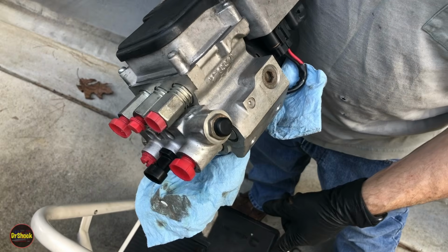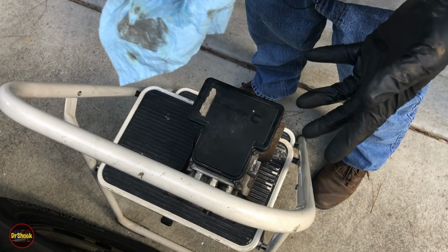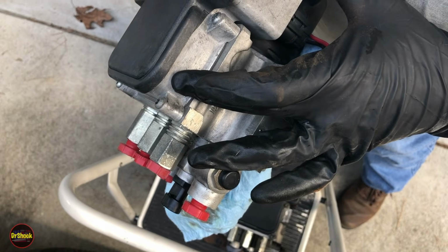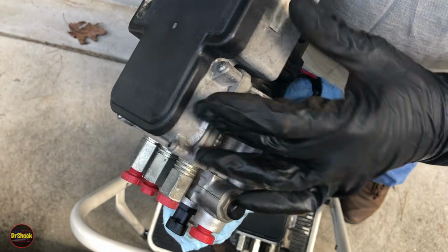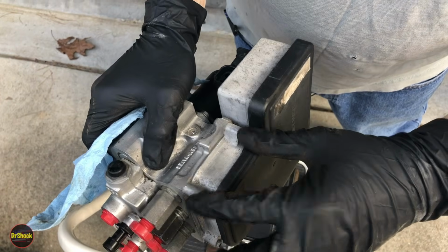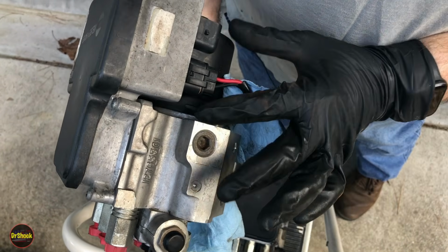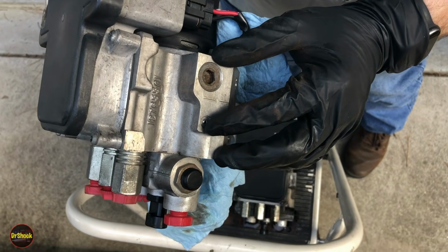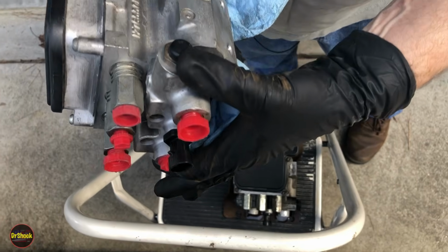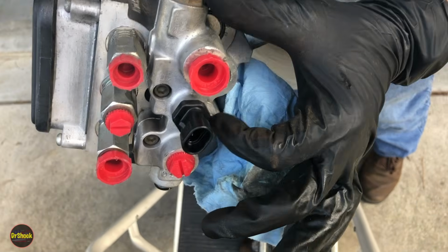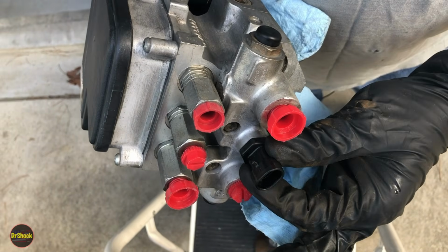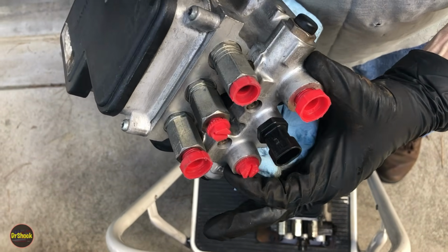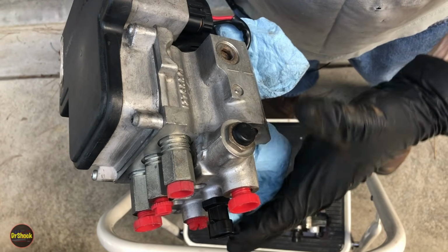Now what I'm going to do is I'm going to go ahead and get this mounted to this bracket, but I'm going to take the old one and I'm going to completely disassemble it for you so you can see the different components, right? So the EBCM that's up here, the electronic brake control module, held on by these 4 Torx bolts. And then this piece here with the pump motor is the BPMV, the brake pressure modulator valve. And then this piece right on the front attached to it with these hex head bolts and also holding the pressure switch. This is the brake combination valve, sometimes referred to as a proportioning valve. So those are the 3 pieces.